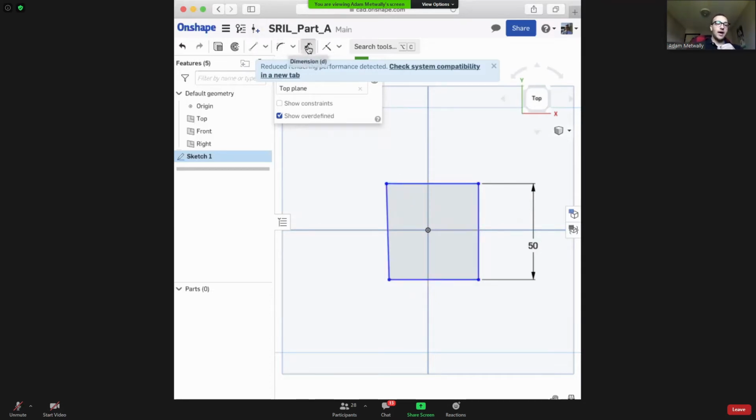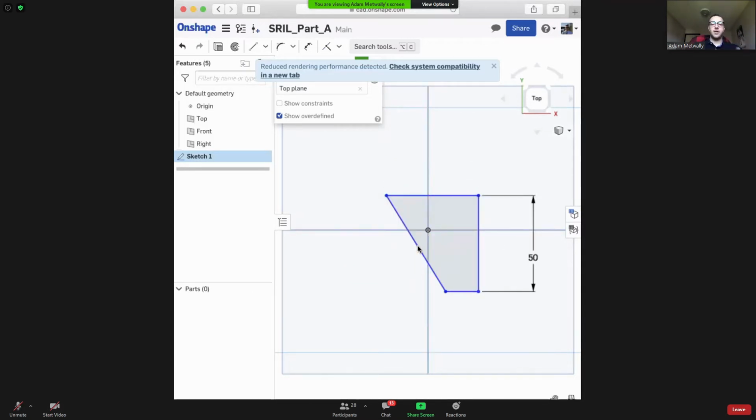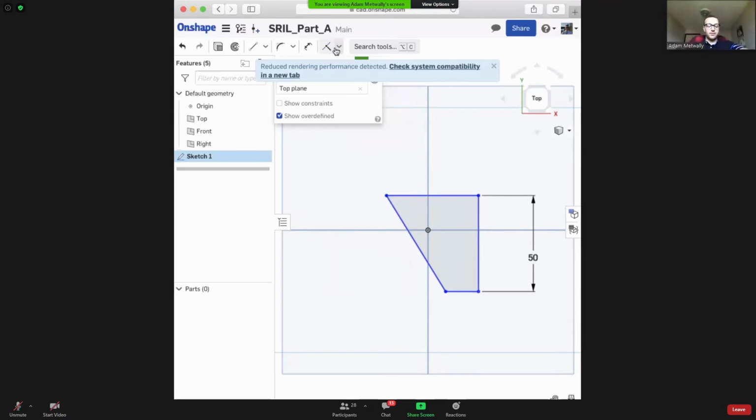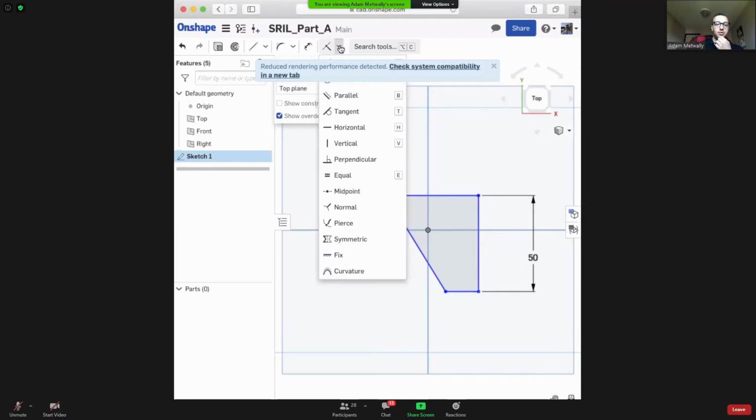Now if I go ahead and dimension this side as well, I want this 50. Another thing we're going to notice is that this is tilted. That's going to get fixed just by nature of this 50 dimension. But if I delete that, there's another way I could have fixed that. Now we can see, oh shoot, I changed this dotted line and now this line has moved. Again, because the sketch isn't fully defined, you can use relations between lines. I know I'm going a bit fast, but hopefully once you start playing around with this yourselves, you will be able to get a picture of this.